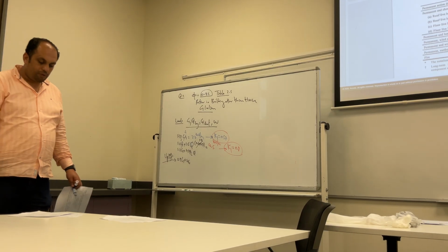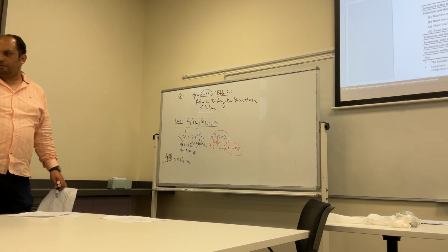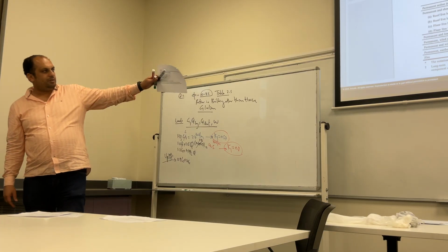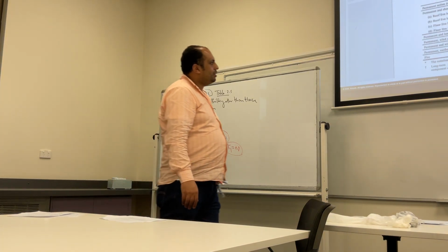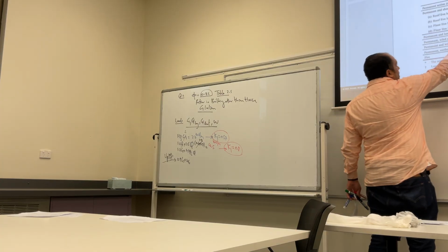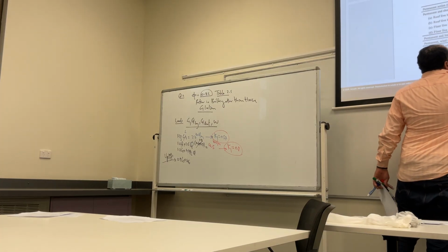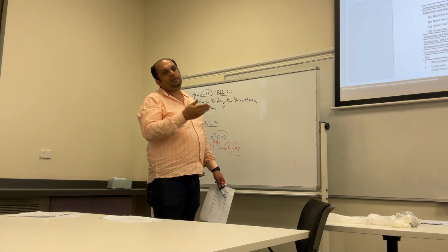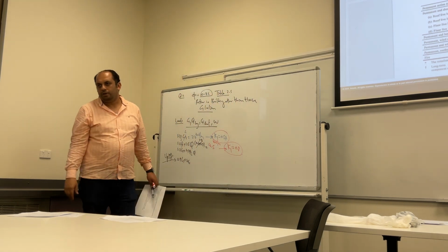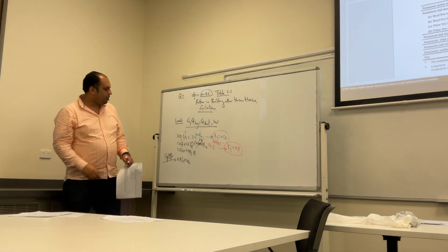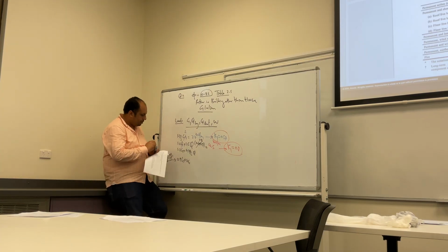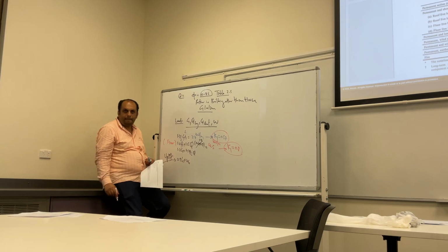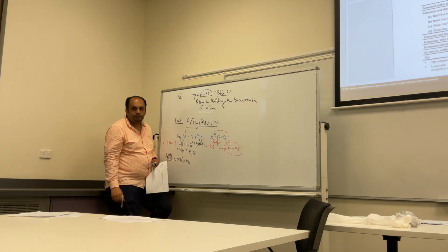Yeah, it can be roof or floor, but it is for the distributed one. So it can be 0.8 or 0.94. If we consider it as a roof beam, you can take it as 0.94. If it is a floor beam, it is 0.8. So I assume here it is what? Floor beam.